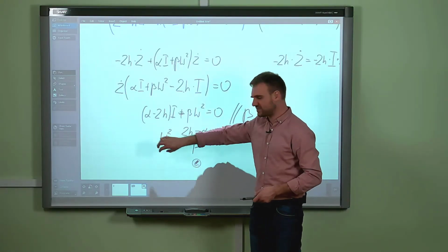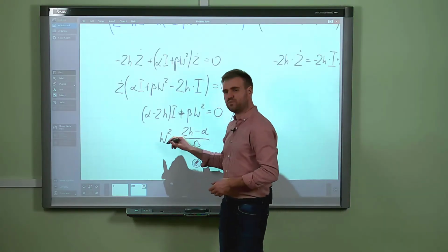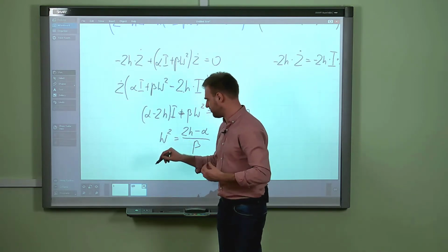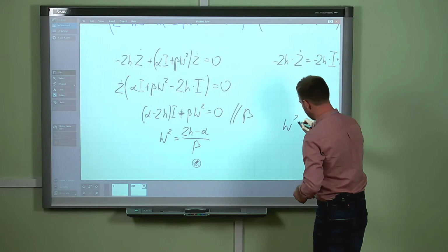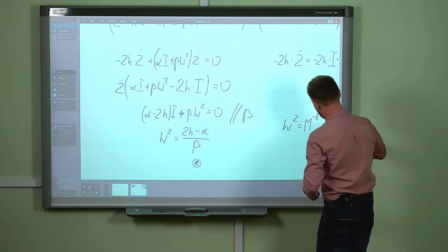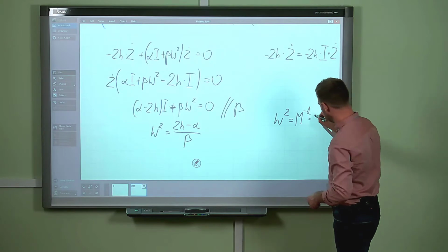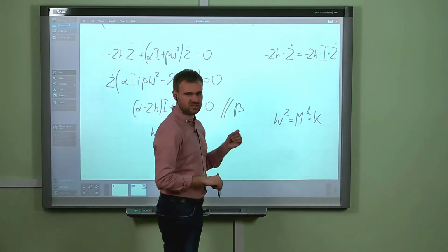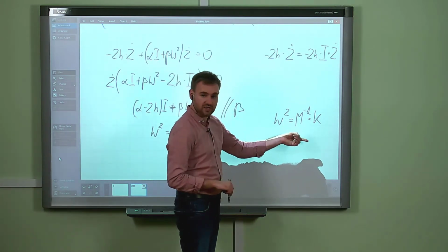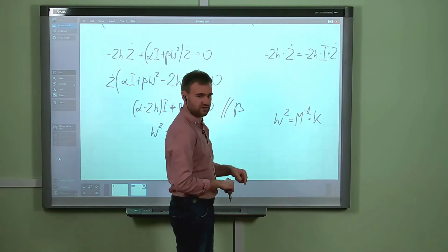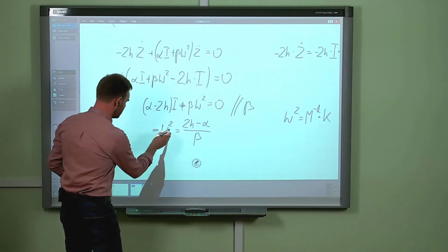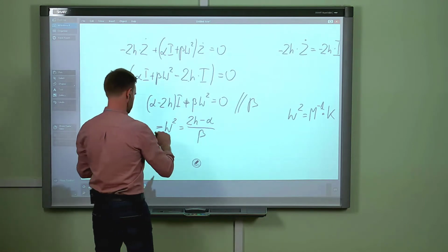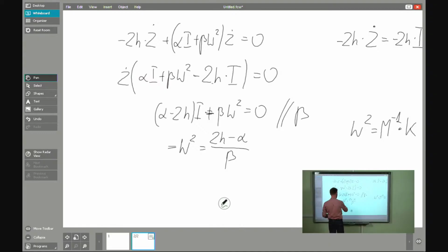We have exactly the same matrix which could be considered if we are talking about undamped free vibration, because the w square is given only by the inertia matrix, I mean the inverted inertia matrix times the stiffness matrix. And if we consider undamped vibration, we are able to determine the eigenfrequencies, I mean the natural frequencies of that system. We know that such an expression, due to the eigenvalues, can be expressed as the omega 0 square